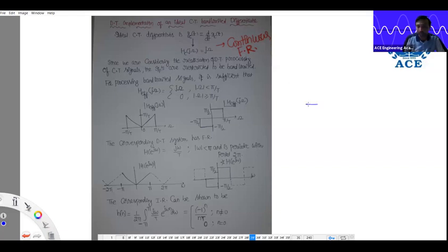Why did I use that? Observe here. We have taken the rectangular spectrum for what range under reconstruction? Minus pi by T to pi by T. So for that range we are limiting. Everyone knows how to draw this graph: 0 to pi by T positive, 0 to minus pi by T, like this. Substitute Omega. This is the magnitude, modulus of j Omega. What about the phase angle? For positive analog frequency it is plus pi by 2, for negative frequency it is minus pi by 2.